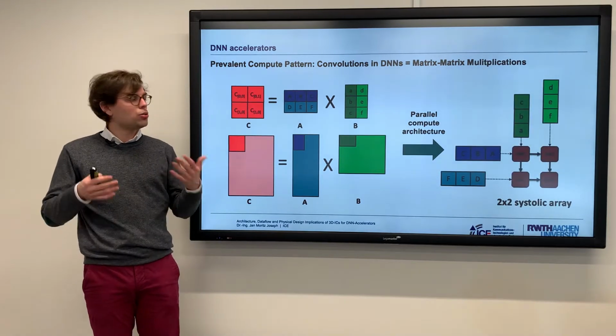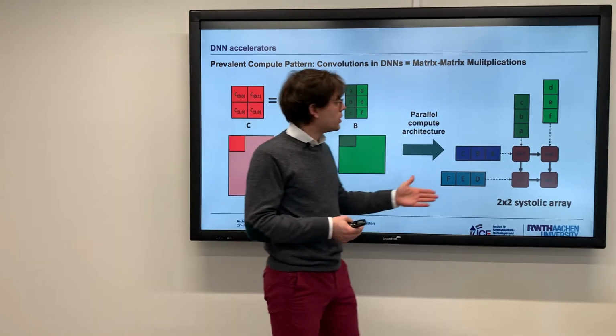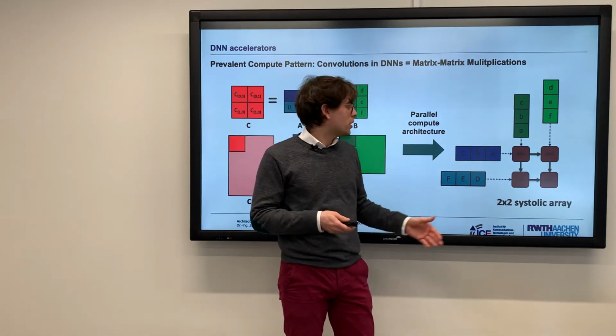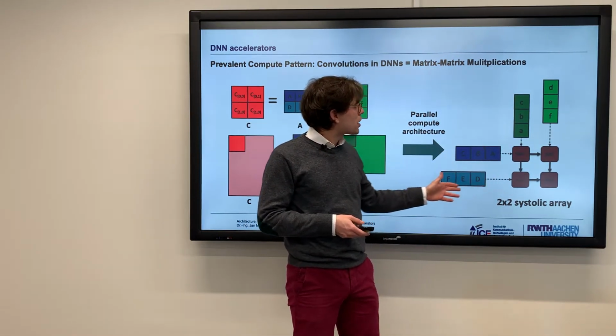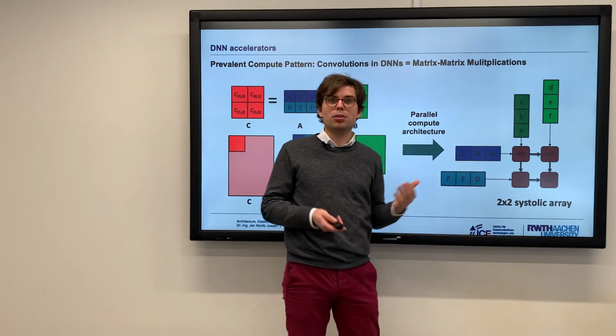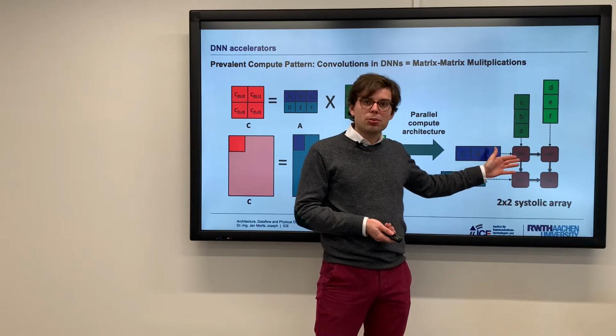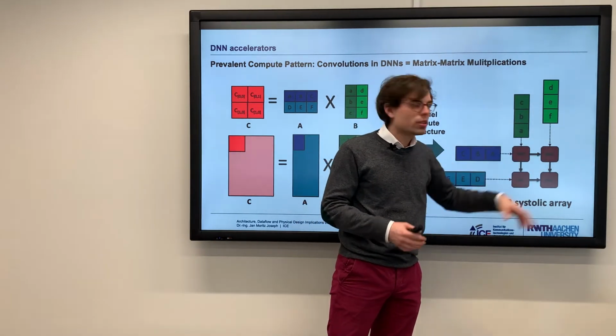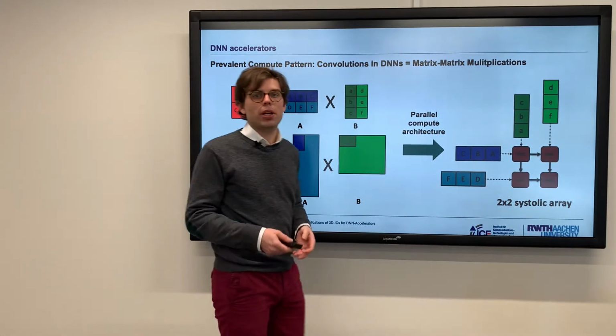In conventional 2D ICs, this is done, for instance, using 2D systolic arrays that yield spatial parallelism. So you have the input matrix coming from the left and the top, and you have multiply and accumulate (MAC) units within your array that do the atomic matrix-matrix multiplication operations, and you have those spatially spread out to do this in parallel.